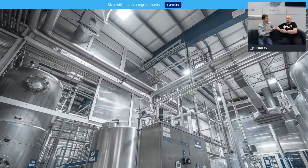And again, we have controlled environment with even lower temperature than the processing of vegetables and fruits, because you cannot expose liquid drinks to higher temperatures and to the infrared or UV radiation, because it would degrade these products. That's especially important when you store them, and you store them in not negative temperatures, because you cannot freeze these products, but they are kept at temperatures slightly above 0 centigrade. 0 to 14. This is usually the requirement. Yeah, and this also again causes buildup of high amounts of humidity in the air. So similar requirements.